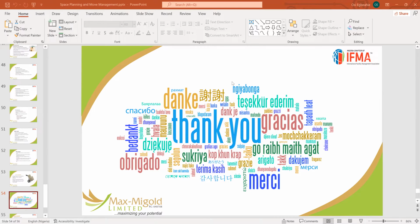Once you add that 20%, that will cater for areas like circulation spaces, corridors, and all that. Once you add that, it should take you to about 400 square meters. That means the minimum space you require to rent, if it's below 400 square meters, cannot accommodate, let's say, 100 staff. So you are looking for something above 500 square meters to be able to manage that. I hope that's clear enough.